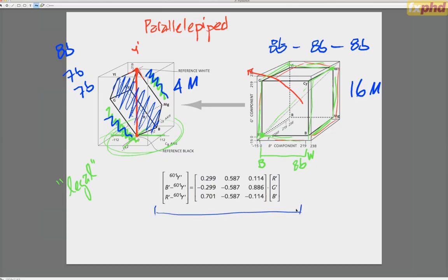The mathematics to do the translation looks like this. It's just a 3x3 matrix. We've got these numbers, which are blue contributes a little bit to luma, green contributes a whole lot, red contributes a fair bit. These weighting factors are a function of the sensitivity of human vision to the different primaries. But here I'm showing you a translation into a rather wacky, obscure space where the math works really well, but it doesn't lead to a convenient set of numbers. So all we do here is scale those numbers into CB and CR.